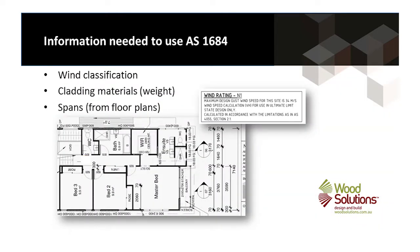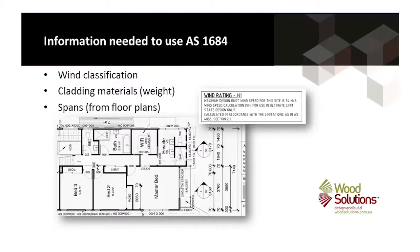We also need to understand the weight of the structure that it's going to be holding up. Roof members are going to be sized differently if they're supporting tiles or if they're supporting lightweight roof sheeting, so that the cladding materials are important in the design of the material. They need to be easily discernible off the plans. And finally, spans from the floor plans are going to be appropriate as well.